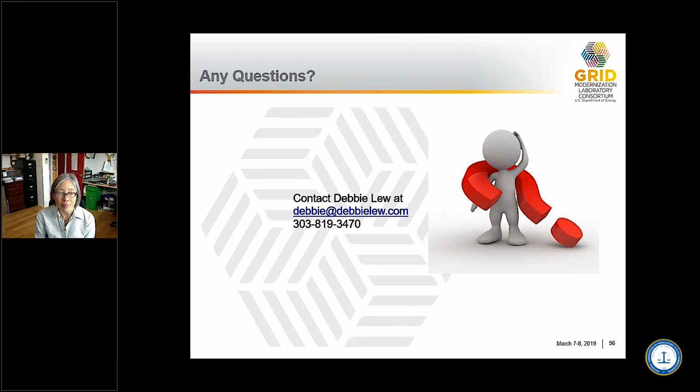And even though storage has a really good grid-friendly aspect in that it's helping to manage all the variability of the solar, for example, right? So it's grid-friendly, and you think, oh yeah, there's not really a negative impact. Well, that's not necessarily true. These things do have impacts on protection, for example, like that whole thing that I just mentioned about relay reduction of reach.